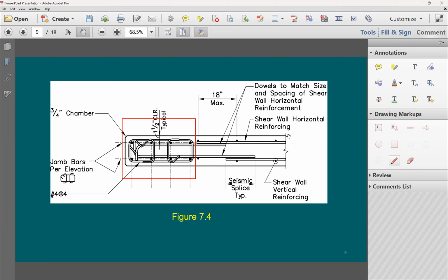First, I'm trying to find out this alpha, the shear factor. So you say HW divided by LW is going to be equal to 1.6. I'm going to take you back to our diagram. If the aspect ratio is 1.5 or less, your shear factor is 3, and if it's 2 or more, it's going to be 2. If it's in the middle, this is the equation you can use to do the interpolation. It says 6 minus 2 times the aspect ratio.